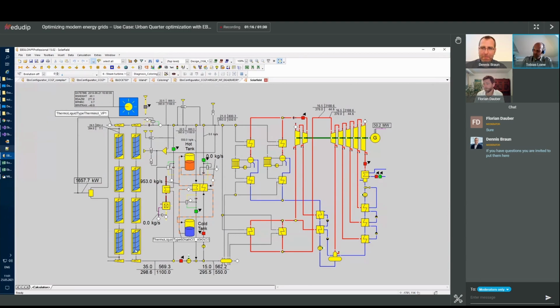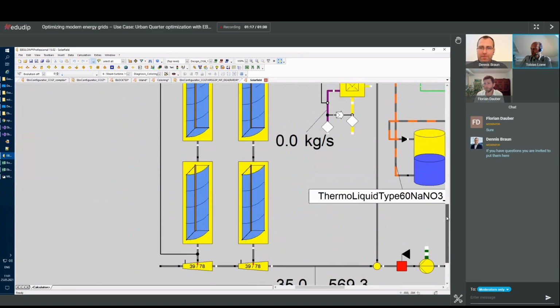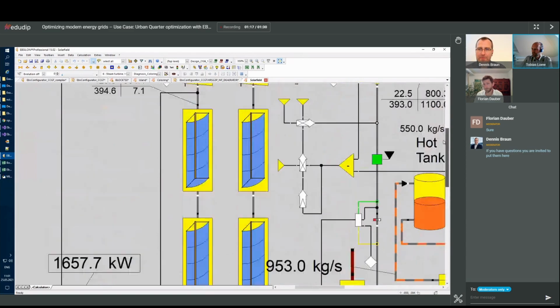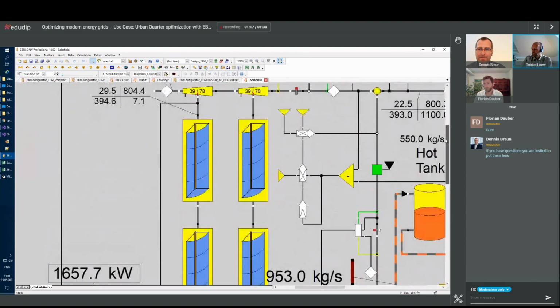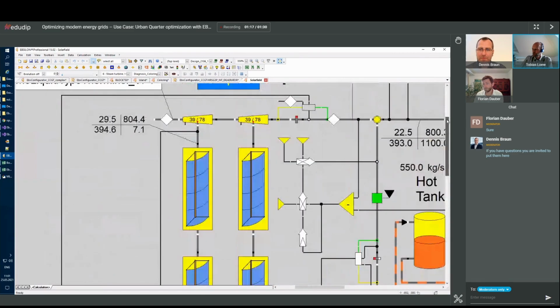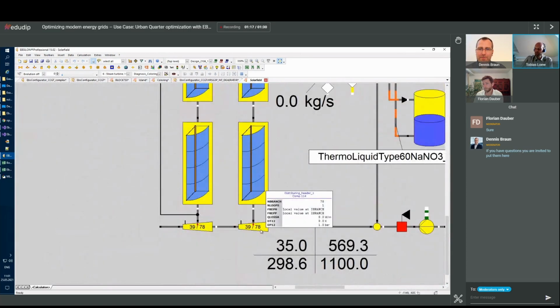and maybe I go in here. You may think we only have 2 rows of troughs in here, but that's not the case. We have 2 lines of 4 troughs. If I go up here, we have a splitter and a header component for those trough systems. All in all, we have 2 times 78 trough rows with 4 troughs.